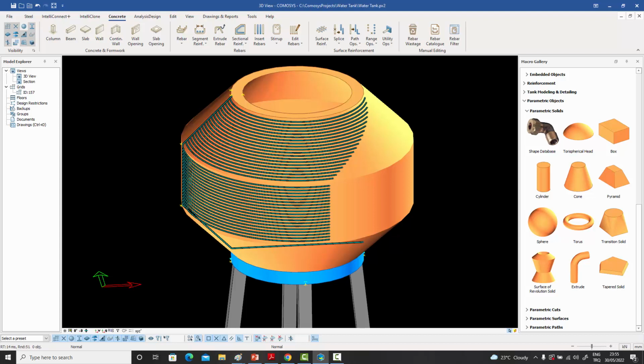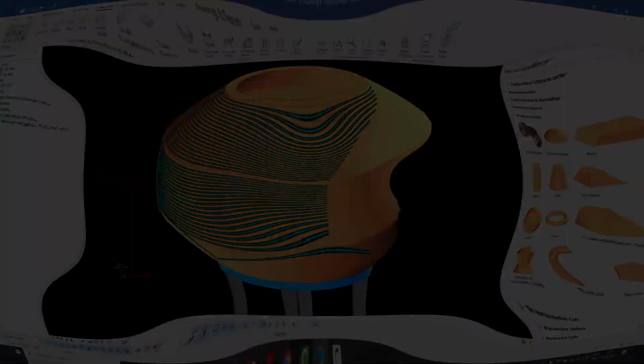But believe me, when you're dealing with prestigious projects, high-end projects, and I'm sure many of you are, you will be doing manual detailing as well, because all those twisted and curved and ridiculous shapes which you will come up with, or those strange looking geometries which the architects will present to you, will not necessarily have macros to get you through them. But what I've tried to show you today is that even without macros, you can do the job pretty easily.